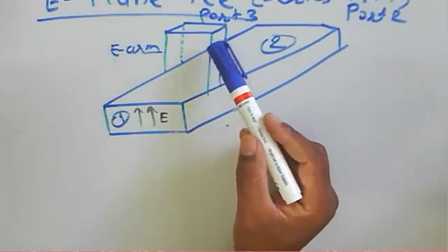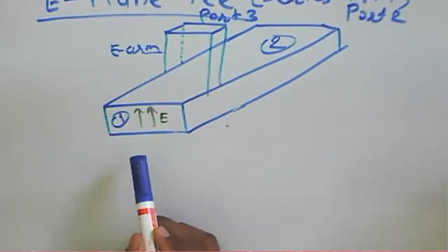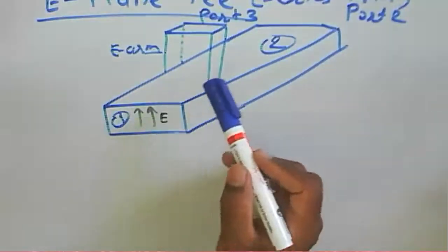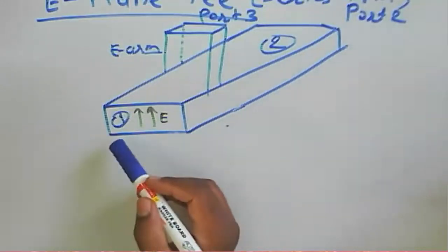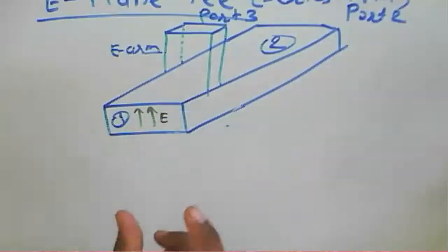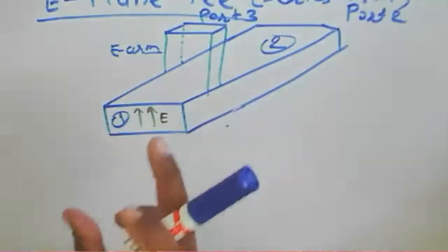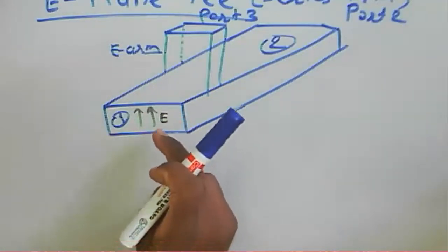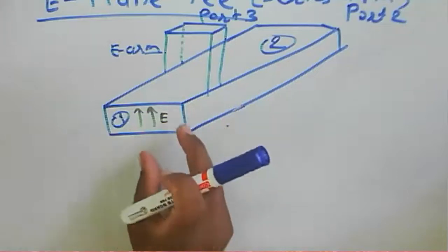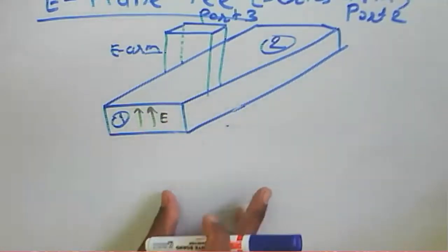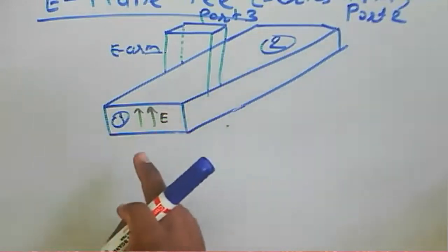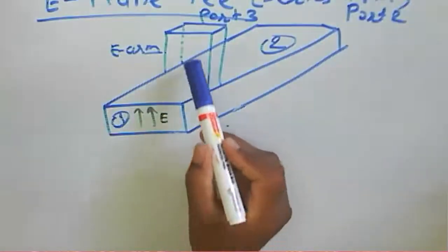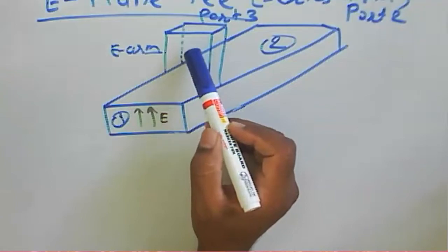Okay, the condition is that the power is applied at port 1 and port 2 as input signals. That will be the same signal from the same source given to port 1 and port 2, but the phase at port 1 and port 2 will be out of phase. If we apply the input at port 1 and port 2 with the same amplitude but out of phase, then it will combine the power at port 3.